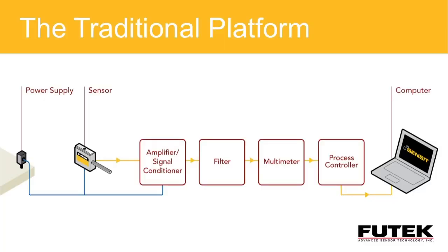In looking at the typical or traditional platform, I'm dealing with a setup usually involving a load cell, analog amplifier, and then I'm going to take my signal and I've got to go into my data acquisition solution. I might also have a separate power supply that I need for my load cell. And in many cases, I'm dealing with multiple suppliers for these components. A supplier for the power supply, a supplier for the load cell, and potentially a supplier for the analog amplifier.